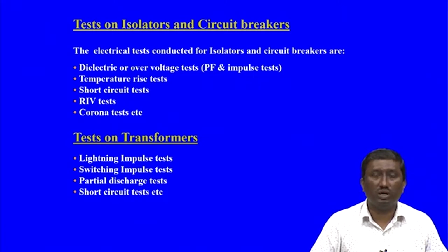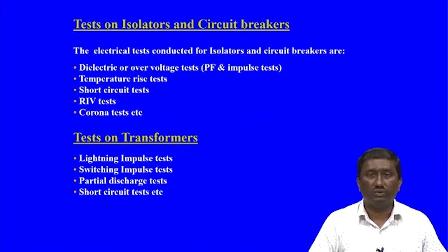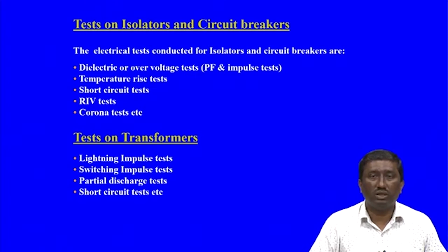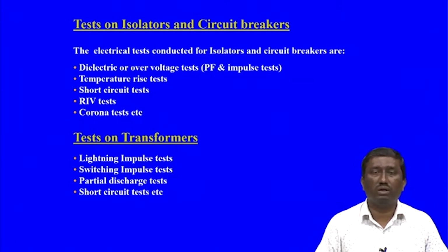Then short circuit test, how is the performance of the isolator or circuit breaker in case of short circuit, that amount of current is applied to the equipment and it is verified whether it could withstand the surge currents during the short circuit of the network which could be seen.